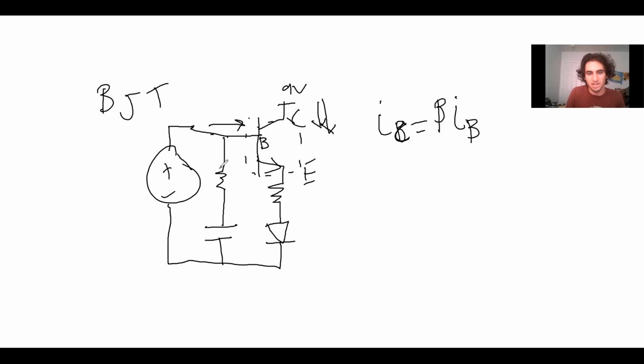But yeah, so basically what's gonna happen is this capacitor is gonna charge up and it's gonna discharge really slowly because, you know, this input resistance is pretty big. And then what's gonna happen is basically the current's gonna get amplified so the LED can still light up. So we still have enough current to light up this LED. And so the LED is gonna sort of get dim really slowly. And the voltage of the capacitor is kind of gonna look like this, right? It's gonna slowly decay down to 0.